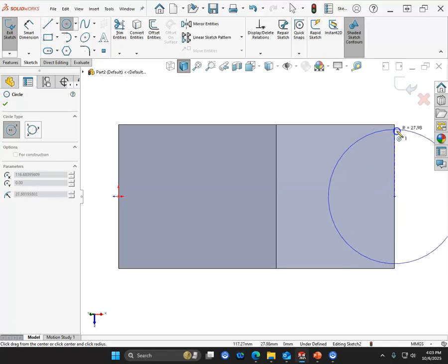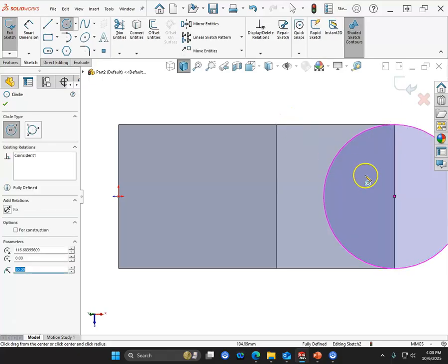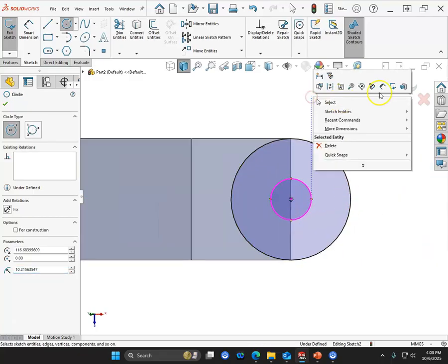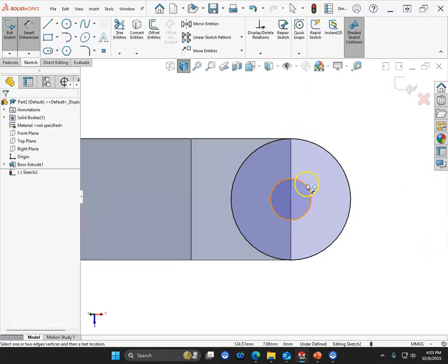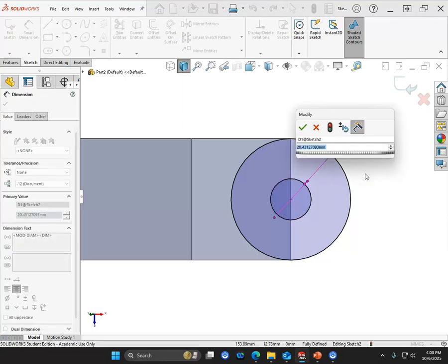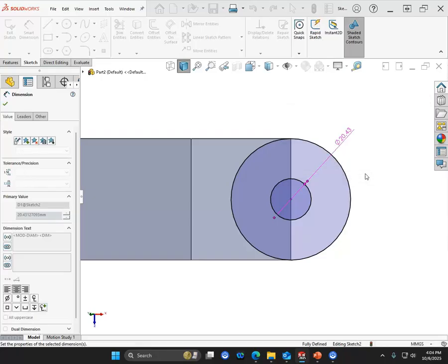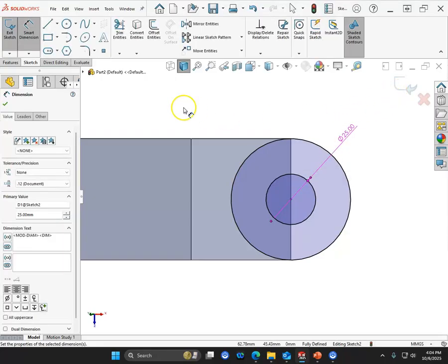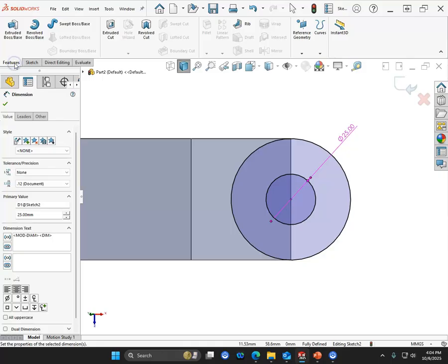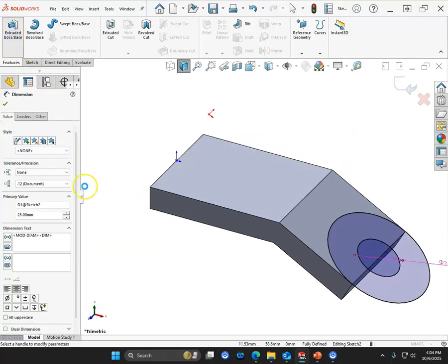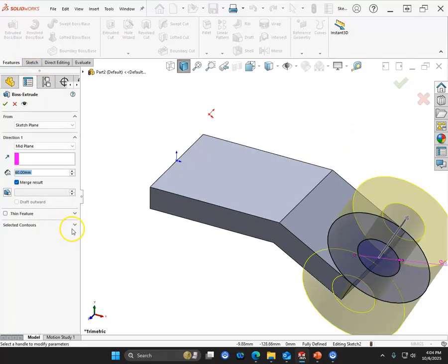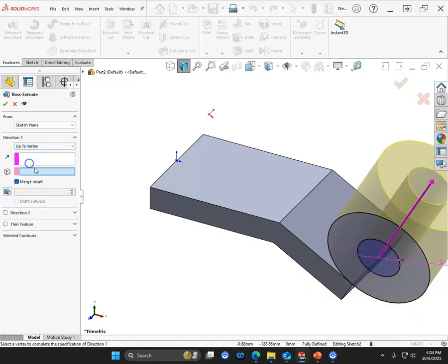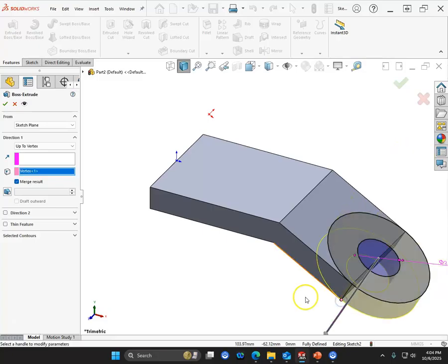So, making this easy, we will draw the two circles. The first one gets defined because it goes coincident with the edge and becomes a 30 millimeter radius. The through hole then is 25. At this point, we can go ahead and extrude. For my contour and region, now we don't want midplane, we want up to vertex so we can go to that geometry.